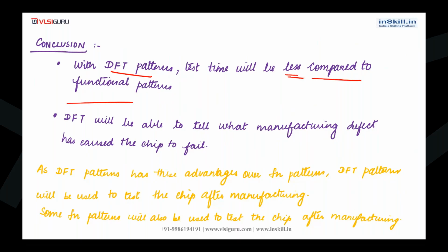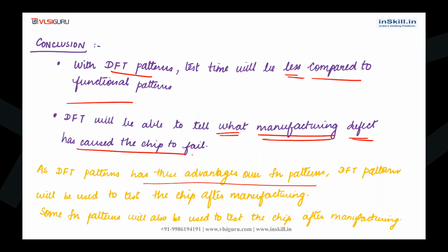With DFT patterns, test time will be less compared to functional patterns, and the DFT team will be able to tell what manufacturing defect has caused the chip to fail.